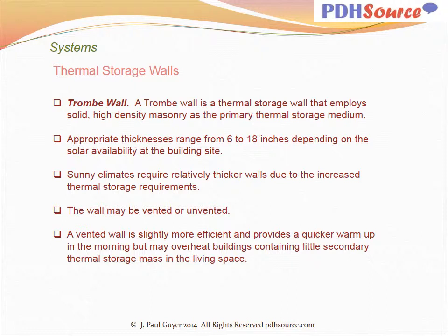The wall may be vented or unvented. A vented wall is slightly more efficient and provides a quicker warm-up in the morning, but may overheat buildings containing little secondary thermal storage mass in the living space.